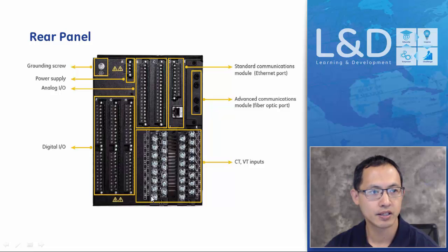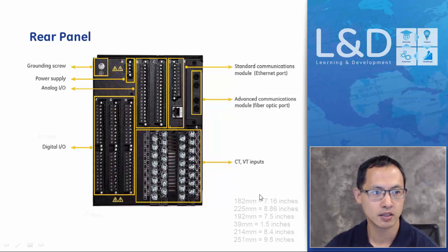For standard 850, it can have only 1 VT-CT inputs on the J card, but the 869, 845, and 889 require 2 analog cards to create the differential protection. So in that case, they need to install both.